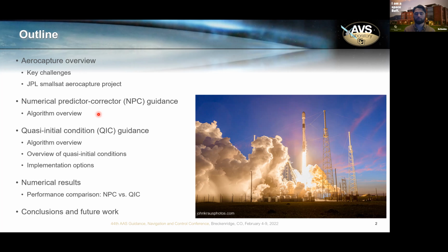You can do simulations and estimate how many it will take, and you can set a maximum number of iterations, but at the end of the day, it's hard to know for sure how many iterations it will take to guarantee convergence, and this makes it difficult to know before you get to implementation if your GNC hardware can actually run this fast enough to converge.